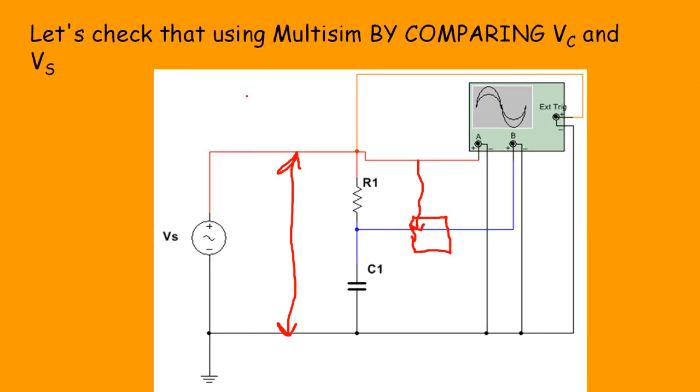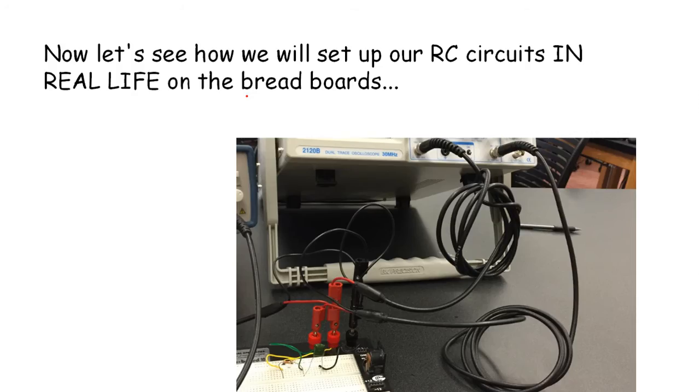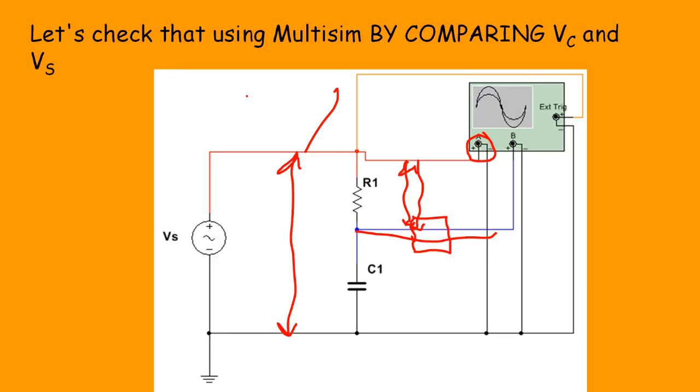Multisim has a 4-channel oscilloscope, which I've never seen in real life, but I guess they exist. I put that on one channel, and then I put the capacitor voltage on the other channel, and then I wanted to put the difference between these two voltages on another channel. But the multi-channel scope doesn't allow a floating ground for each input, unfortunately. You'd think in the fairy tale world of Multisim they would allow such a thing, but they didn't. But let's see what they did allow.